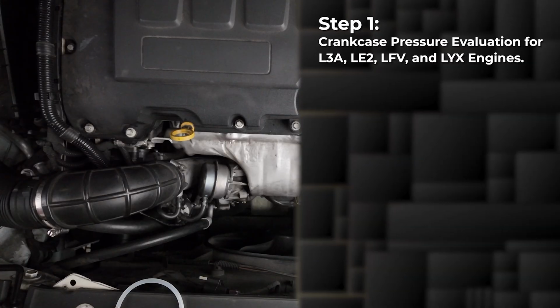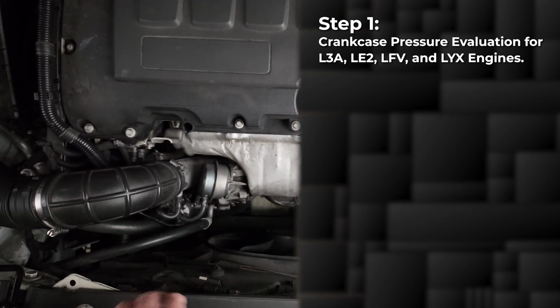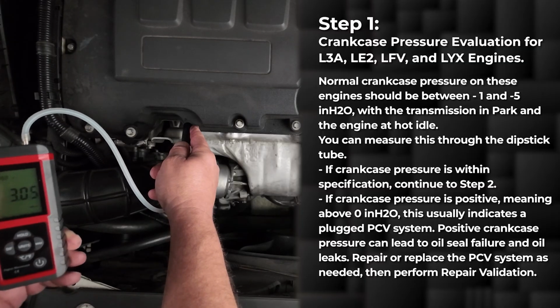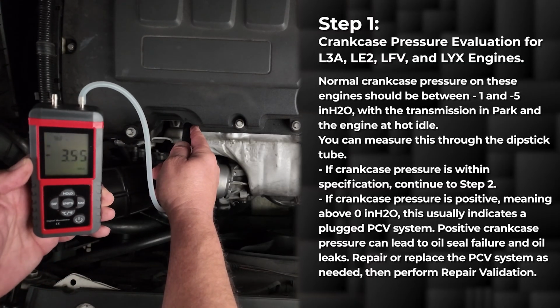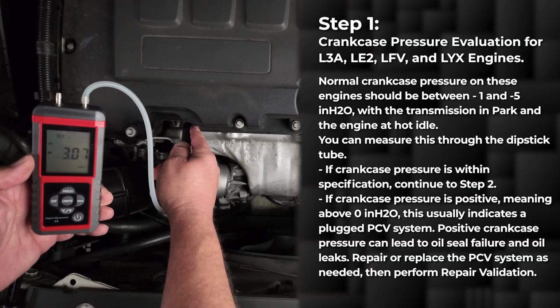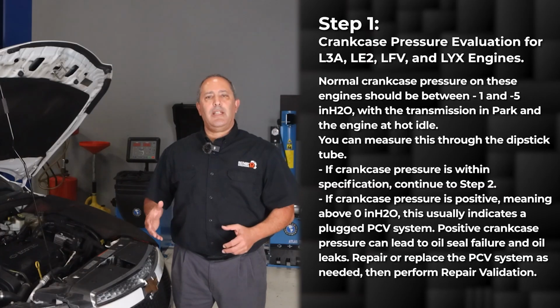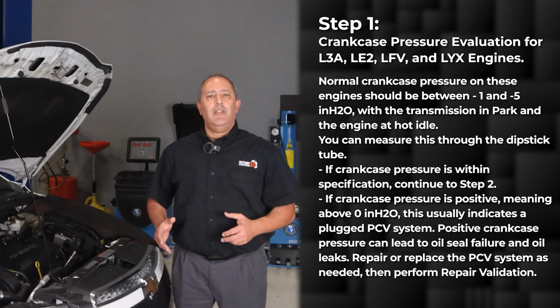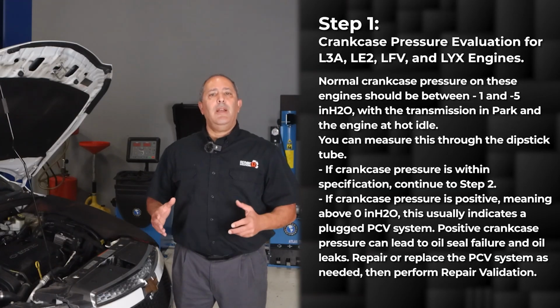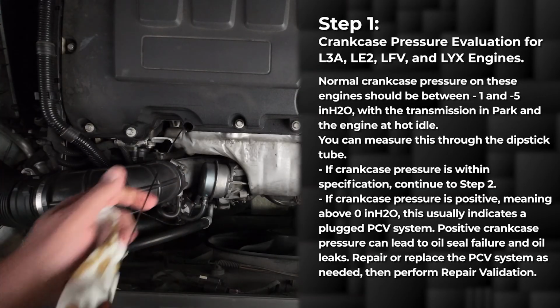Step 1, check crankcase pressure evaluation for L3A, LE2, LFV, and LYX engines. Evaluate the crankcase pressure on the engine. With the engine at normal operating temperature, the transmission in park, and the engine idling, crankcase pressure should typically measure between -1 and -5 inches of water. This measurement can be taken through the dipstick tube using a manometer. In this case, the crankcase pressure reading falls within specification, indicating that the positive crankcase ventilation (PCV) system is operating as intended. Continue to the next diagnostic step.